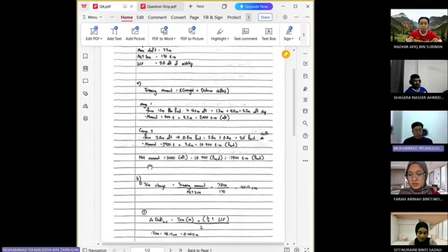For the net moment of the cargo, you basically just subtract cargo 1 from cargo 2, which is 2,600 TM aft of the ship minus 10,440 TM forward of the ship, and you get 7,840 TM forward of the ship.